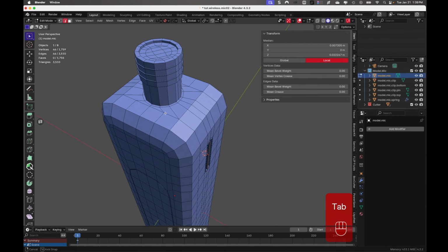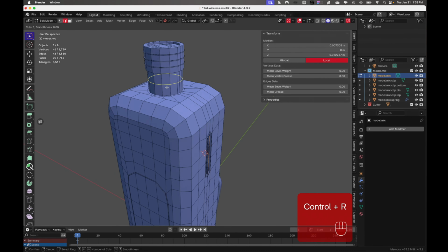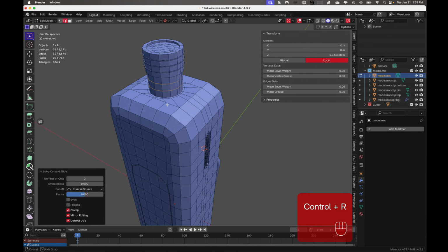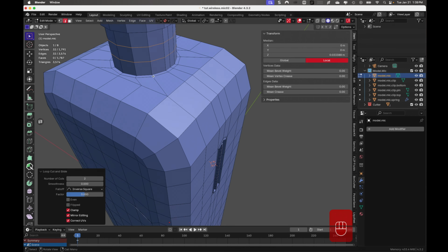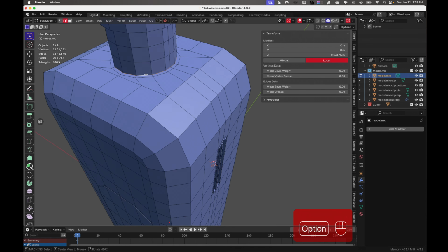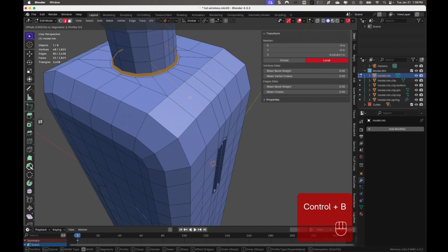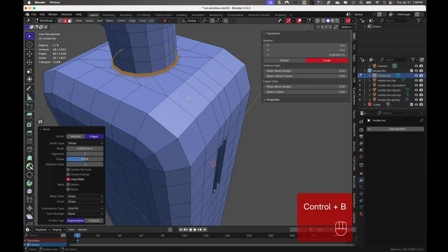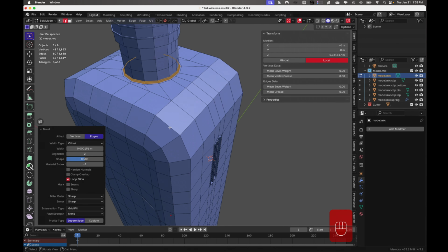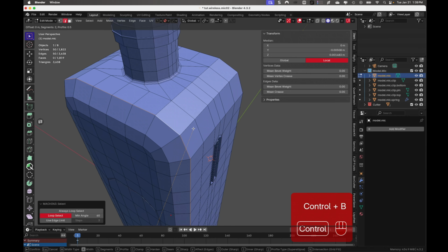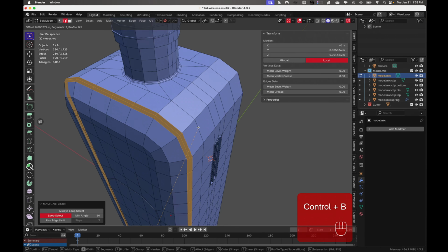All right, so now let's do some geometry cleanup. I'm just adding in support loops and bevels wherever I need to. So when we run sub D on the body, we can be assured that it's going to keep the structural integrity of the shapes that we've created in here.